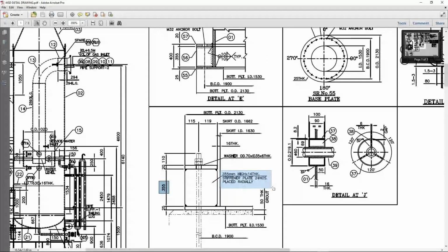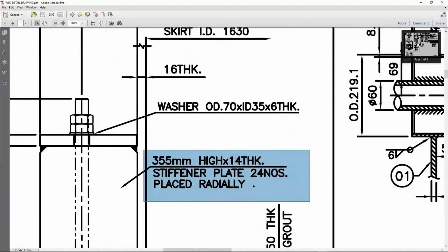Here the rib thickness is 15 millimeters, and we have a top ring. So let's select the top ring from here. Define the radial. Let's make it the same as the hole diameter of the top ring. That's the base ring. Here, that's the top ring. It's the same, 38. Okay. And the top plate thickness. Back here, the thickness is 20 millimeters. Okay, so let's define it as 20 millimeters.